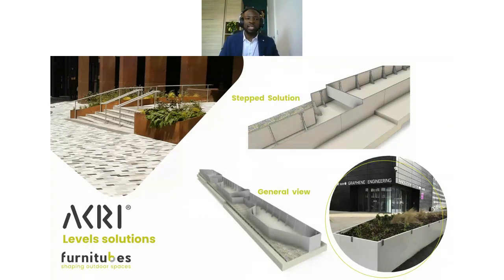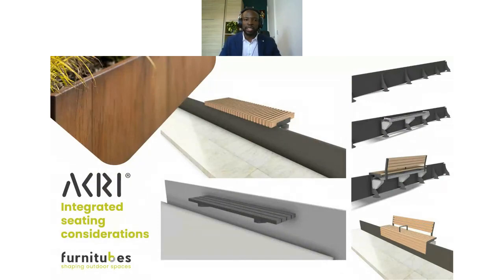There are things to consider like the shadow gap as well when you're using Corten, as this might be required to avoid leaching onto the surrounding hard landscape. These are all things to consider when designing these.